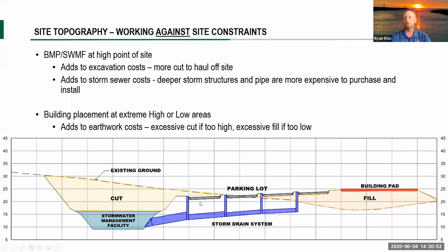If we go into this and just blindly think that cut can balance fill, we may be surprised during construction to find out that we've made this decision, but we've got some really terrible material in this hillside that can't be utilized. And so all of this needs to be hauled off. So it's a dangerous assumption to make right up off the bat that that's something that's going to happen. You want to have a little bit of backing information, especially if you're going to have excessive amounts of cut